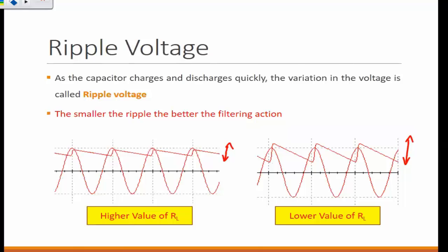But this technique of increasing the resistor value is not that commonly used. As I said, the resistor is considered a load, which the designers don't have control over. So it's largely the capacitor. According to the formula, it's either or: you can raise the resistor or raise the capacitor.